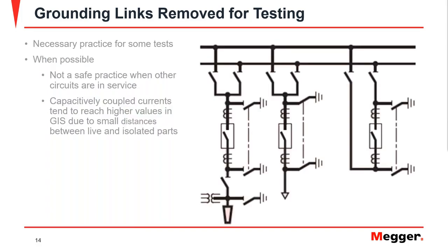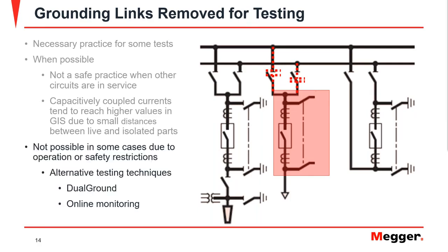Here's a little bit more illustration about it. In this case, we have this bay here grounded. Because it is grounded, it's kind of a safe area. It's no problem, you can easily work there, even though you still have the capacitive coupling from the other two buses. If the buses are energized, they are going to be inducing there, but everything's grounded, so you don't have any problem. If you remove the grounds, now it's not a safe area anymore. So that's what happens.